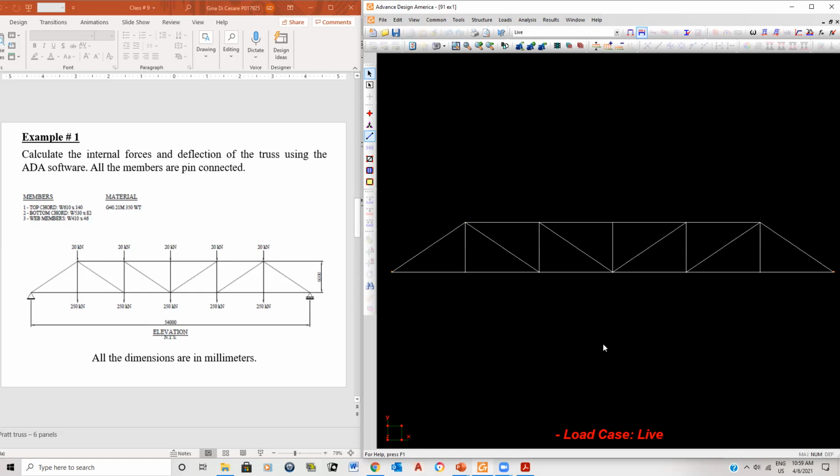Now, here you'll notice that all the loads for this bridge have been assigned to the panel points. So what you should do is activate the nodes on the vertical column. That's number 1, because this way when I go to pick something, I'll only pick the nodes. Number 2, you notice that they have exactly the same value, so I can pick more than one at a time. So by window, I'm going to make a window. Believe it or not, I just picked all the top nodes. I don't know if you guys can see it, but it's yellow.